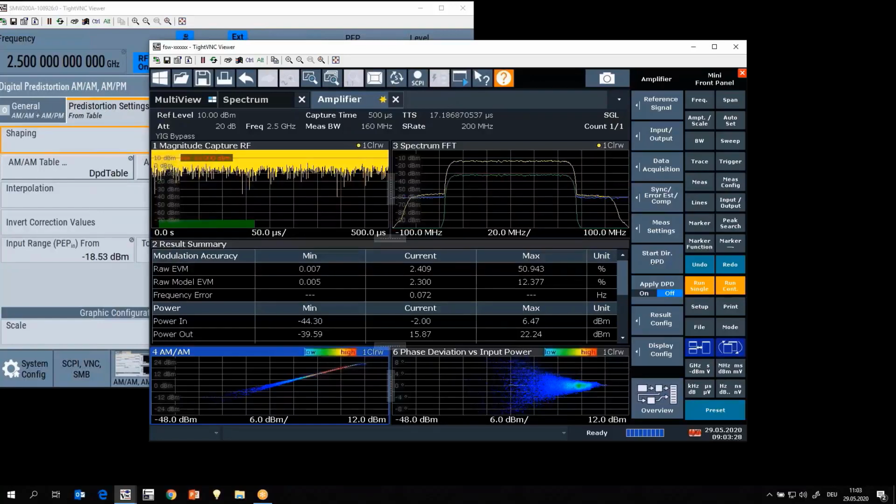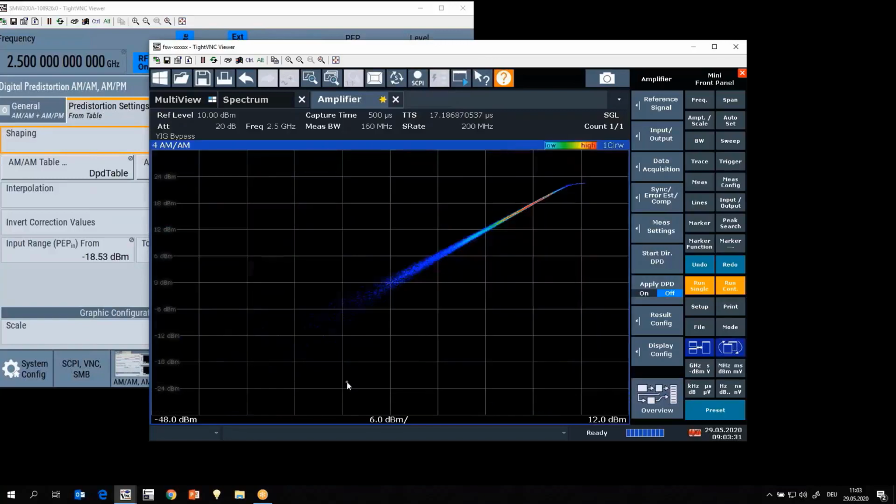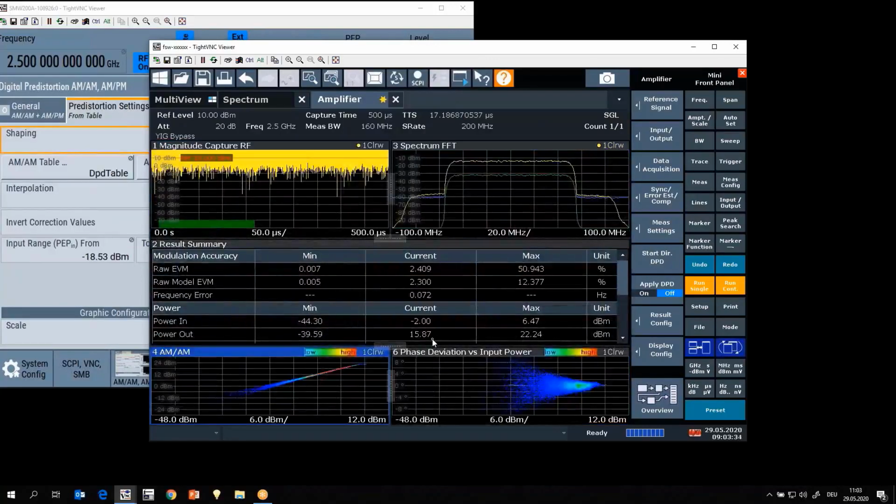And as I said, we don't apply any model, even though the modeling traces are still active here, just in case someone notices. But basically what we're doing here is comparing the reference signal, which is in the spectrum plot, the green one, with the measured waveform sample by sample. And for each sample, of course, the measured signal is scaled down with the measured gain. And for each sample, we compare the difference in amplitude and phase and correct that accordingly.